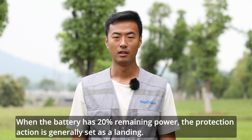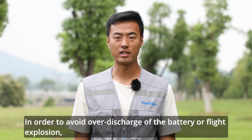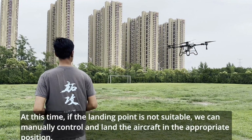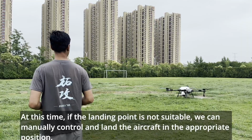When the battery has 20% remaining power, the protection action is generally set as a landing. At this time, the battery has lost power and cannot support safe return. In order to avoid over-discharge of the battery or flight explosion, the aircraft will slowly land after 10 seconds of triggering. At this time, if the landing point is not suitable, we can manually control and land the aircraft in the appropriate position.